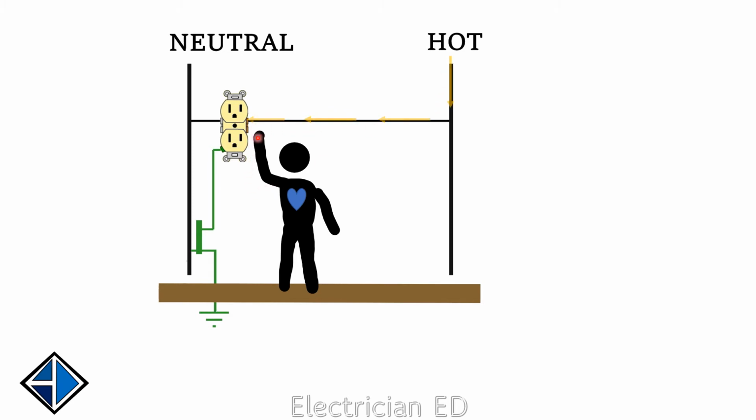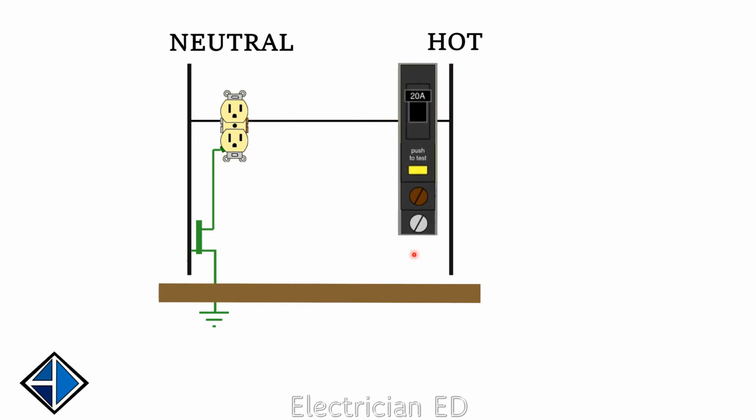Now we've just got voltage again. And this is an open circuit again. But there's a better way to do that. If you can't let go. Normally, if you got shocked, even if you froze up on it, the weight of your body, you would hopefully pull yourself off of that connection and stop the electrocution before you died. But we don't want to depend on that happening. So let's introduce a GFCI breaker in this case. And these hook up a special way.